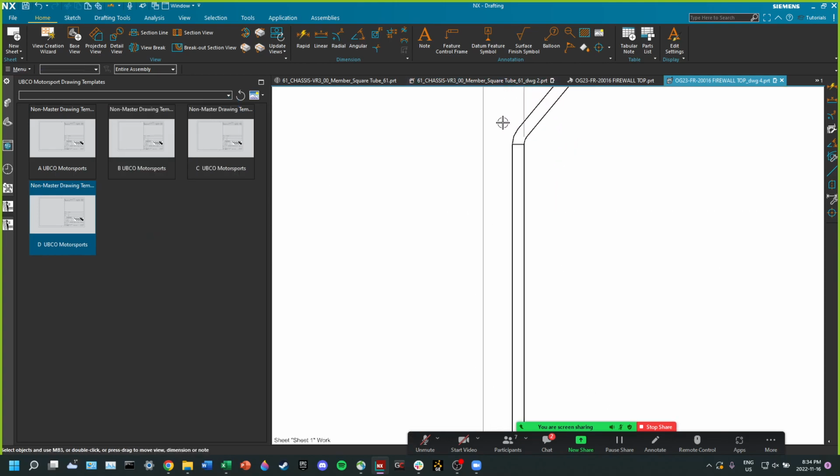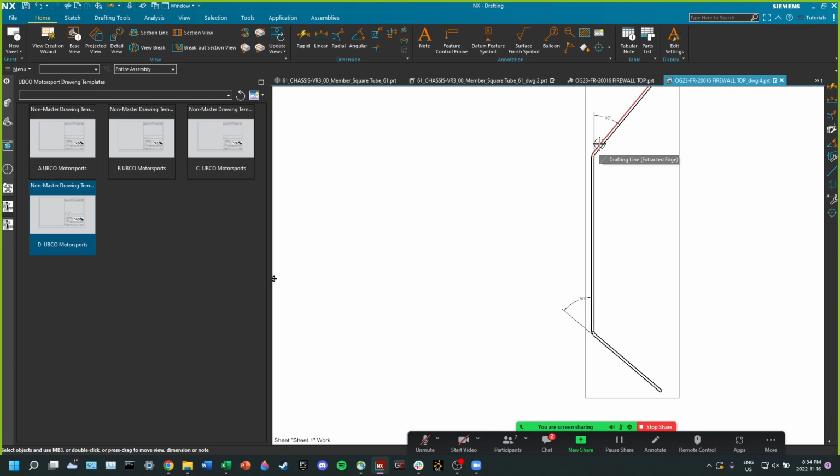But the example that I want to use is the hub, for example, where you're going to have certain lengths along that hub that need this diameter for this long, and then you're going to step the OD to this for the bearing and step it back down, sort of thing. And so there's where you want to have a solid reference datum, reference your dimensions off of that datum, and have one point that you're dimensioning from.